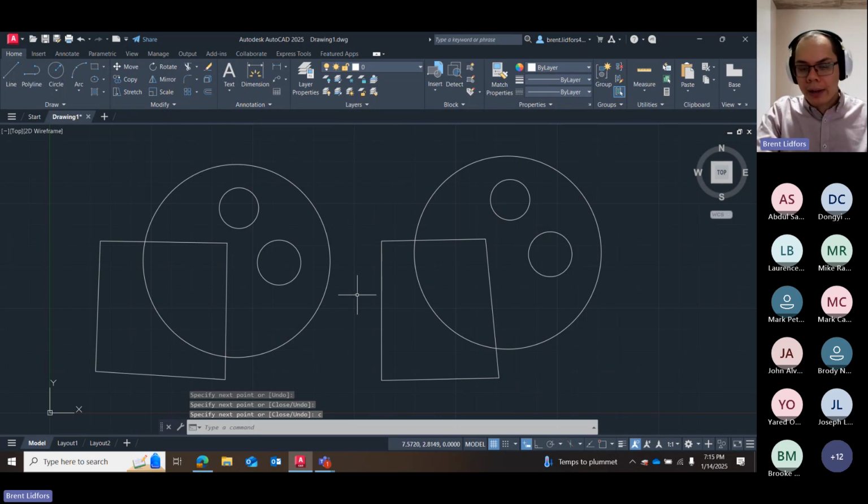So if I now want to go back and join these lines with the line tool, it becomes a pain selecting it all. Because if I want to just manually group it, I accidentally group other things along with it, unless I use a crossing window. I could grab it, but it causes a bit of tedium and a bit of headache down the line.